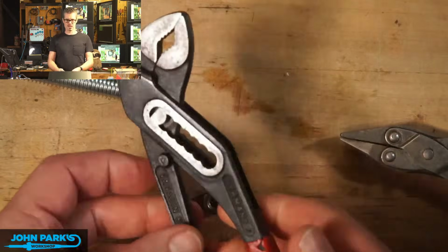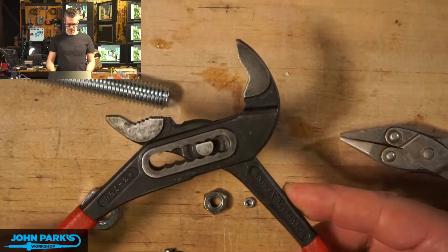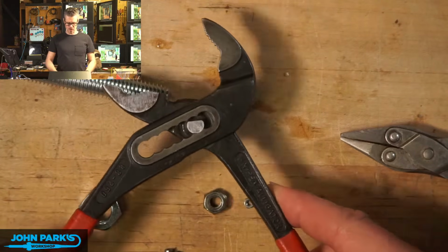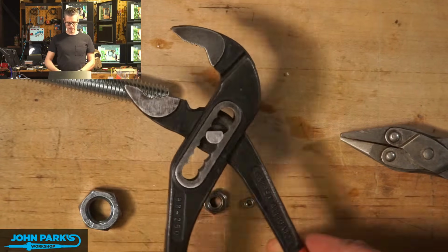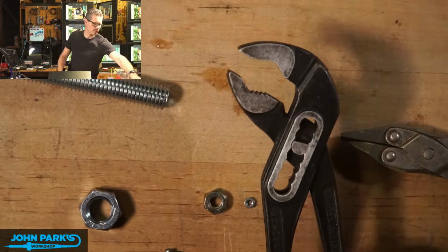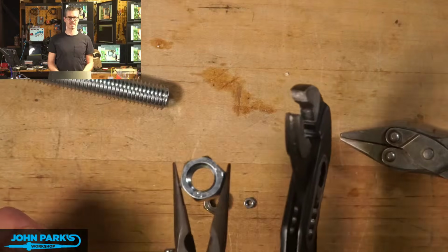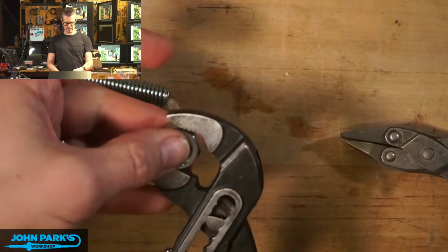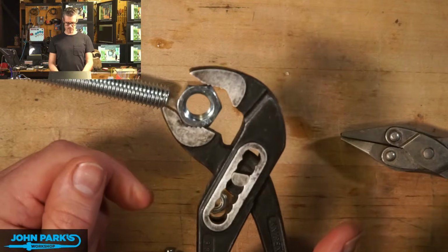Another part of this story is I've had a nice Knipex pipe wrench, or what do you call it, a heater wrench, forever. So these are also adjustable. You can pick the size. These have not got parallel jaws. They're a little closer to parallel than something like a regular pair of pliers, which is a disaster for this type of thing because you're never going to contact two of these walls at the same time. This has some geometry where you can get pretty good purchase on things. So these are real nice.